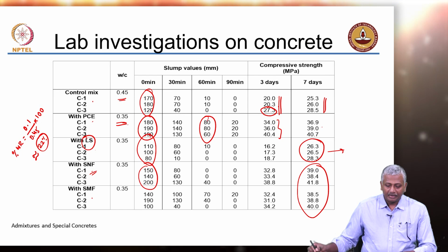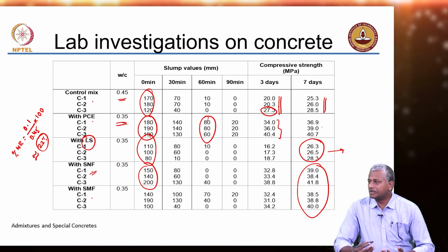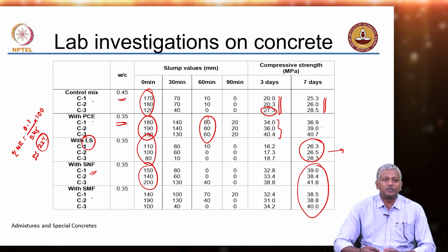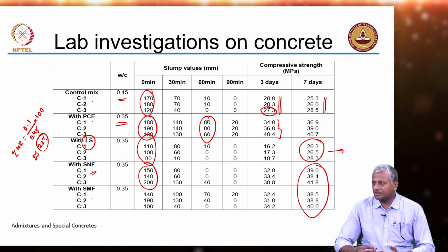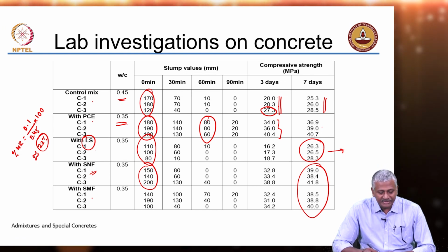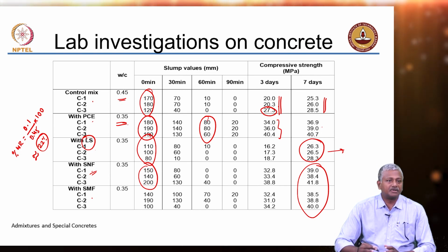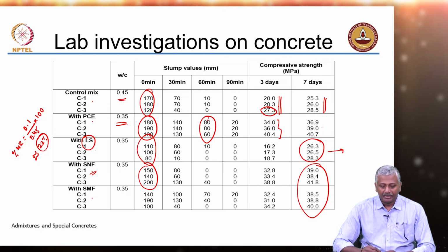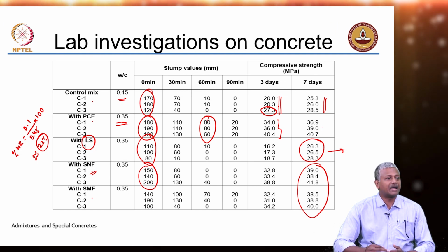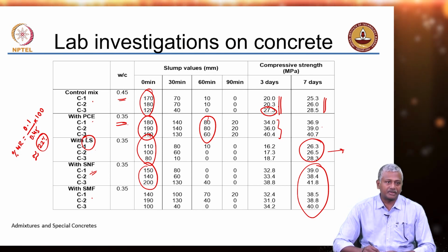So, as we had discussed previously, when we look at this determination of saturation dosage in the paste, we can actually start making concrete with the similar dosage and expect a certain level of performance. I was talking primarily about this example where we looked at 3 different types of cements in conjunction with several different families of superplasticizers, and very clearly you could see that the one superplasticizer that did not really have a major problem of compatibility was the polycarboxyl ether, right.